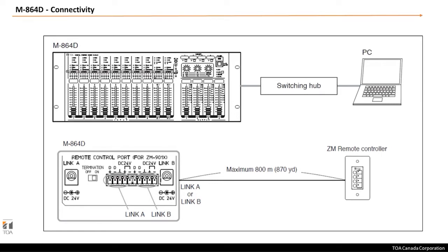Over the years, we did have some people utilizing non-shielded cable, and some problems were occurring with non-shielded category cable, Cat5 or more. I mean, it's not important to really use the latest category cable, but it has to be shielded.